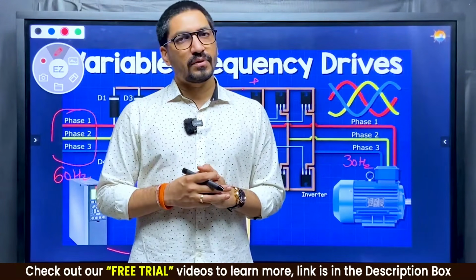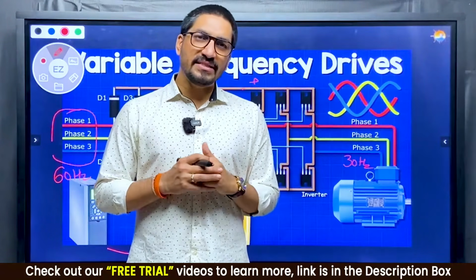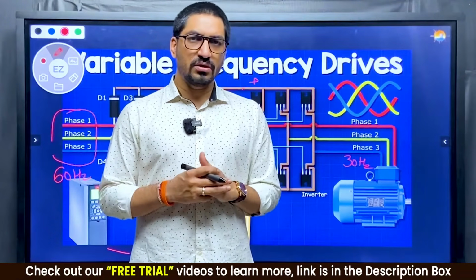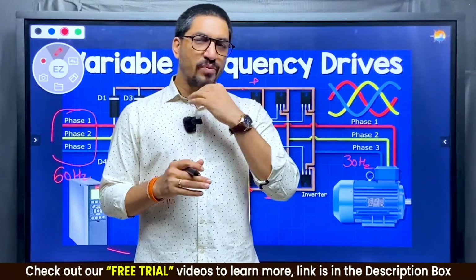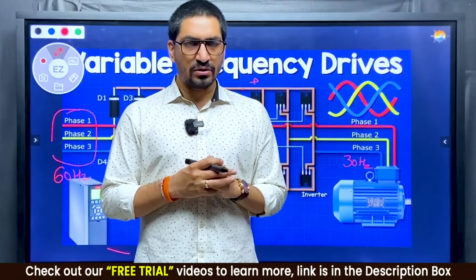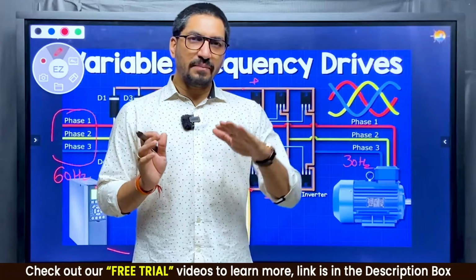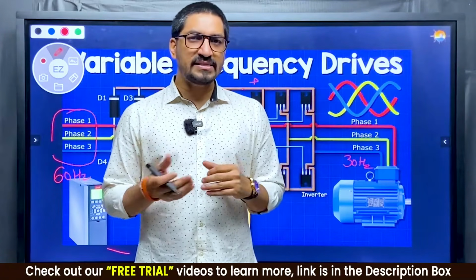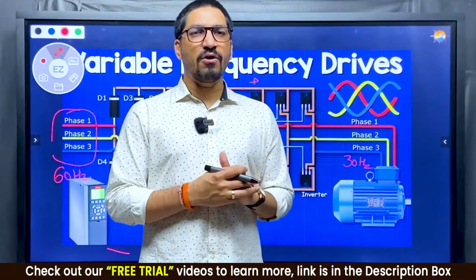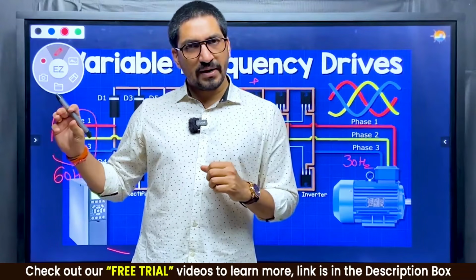on the deck. In the engine room, there's a machine called an incinerator which is burning sludge, and the temperature is to be maintained around 900 to 1100 degrees Celsius. So how is the temperature being maintained? If the temperature is falling, you need to increase the delivery feed rate of the sludge, and that is coming through a positive displacement pump.